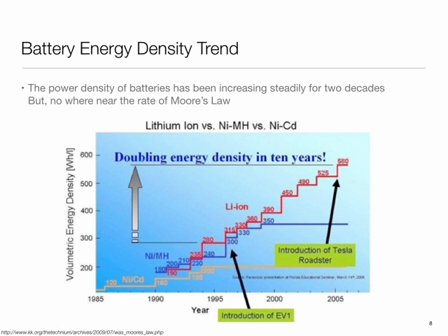To give you an example, in the earlier days, lithium ion batteries had a higher degree of impurity. But over the years, they managed to make the chemical inside the battery more pure. And the effect of that is that batteries age less. So if you look at laptops from 6-7 years ago, their batteries were usually rated at around maybe 300-400 charge-recharge cycles, and then the batteries were basically useless.